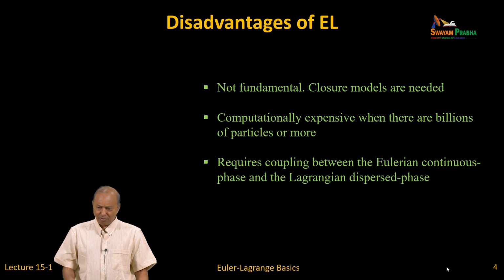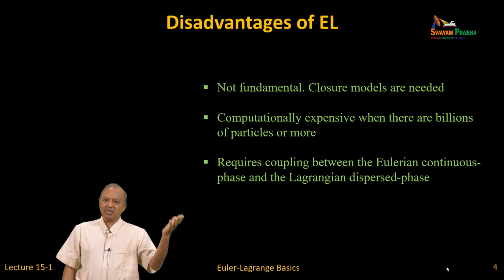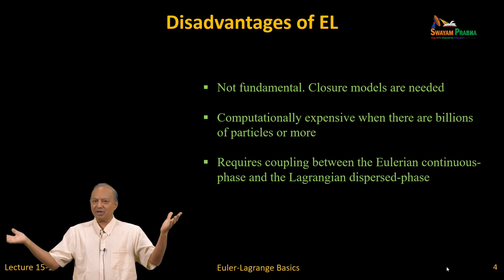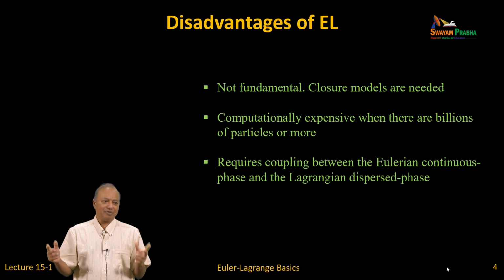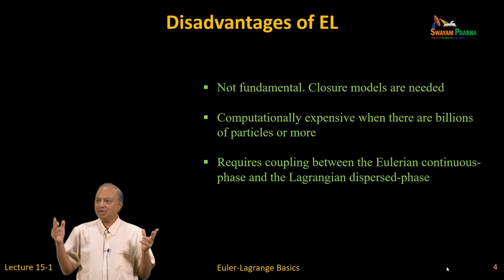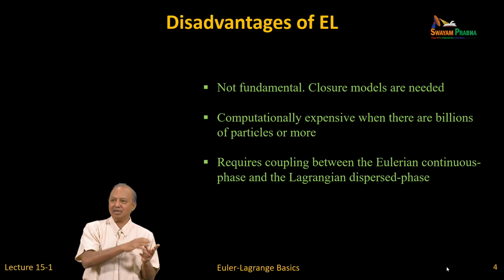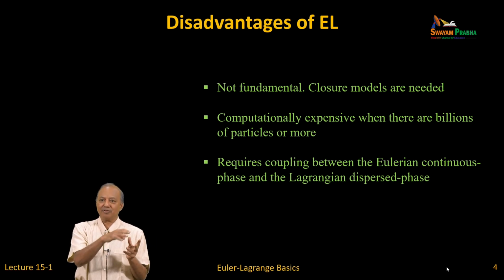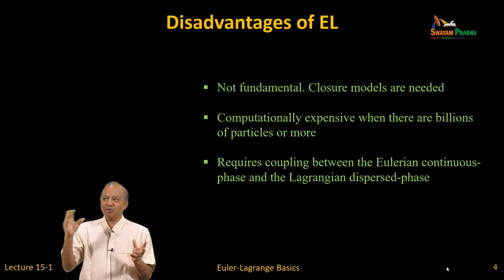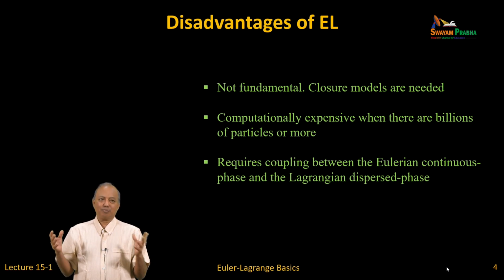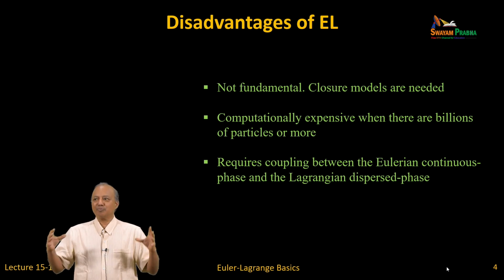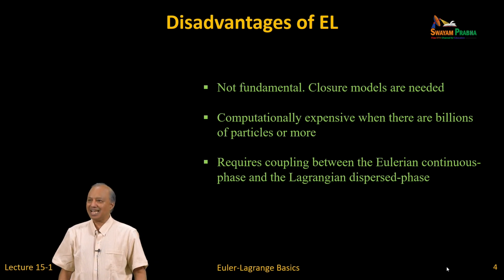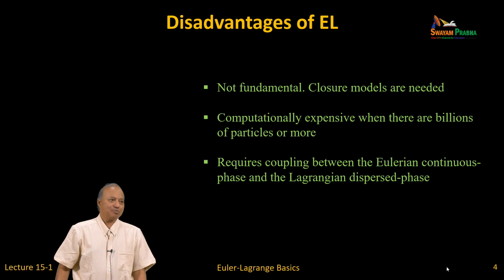But here one issue is that when you have particles as Lagrangian and fluid as Eulerian, you have to think in terms of interpolation from fluid to particles, and then if you have two-way coupling and you have some heat transfer, some drag, you have to put it back. Are you going to spread it over your cell, or are you going to spread it over the nearby 9 cells? Because smoothness, etc.